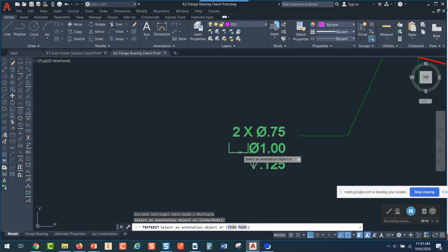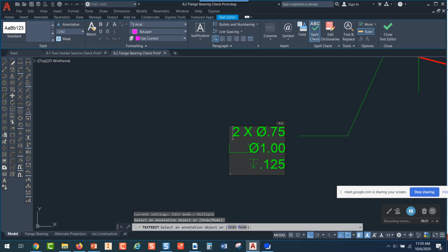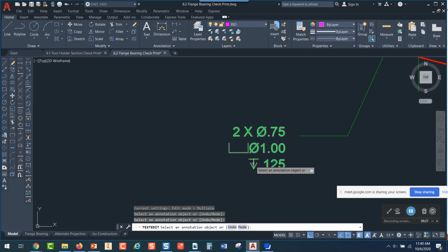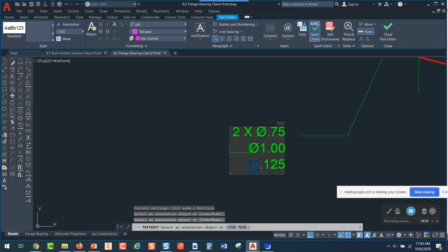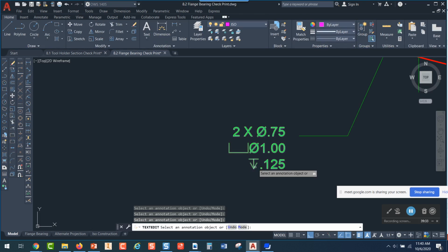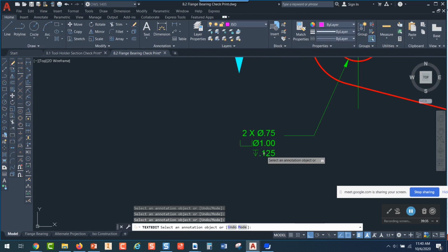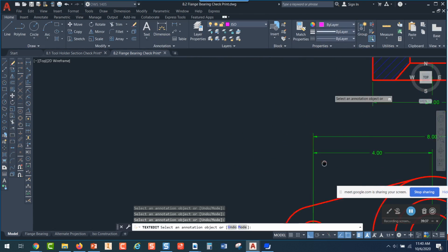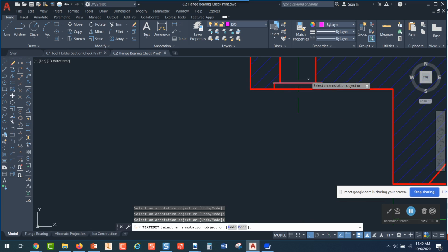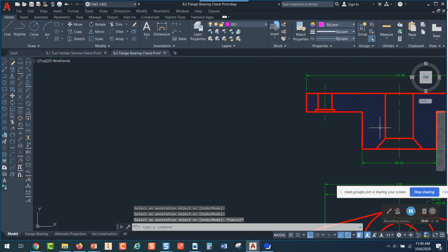Same thing happens over here. You're going to put a lowercase v in right here and then change it to GD&T. Then you're going to put a lowercase x in right here and change it to GD&T, and this is the depth symbol. So that's the depth of the counterbore. So when you see the depth, like right here, that's what that is.